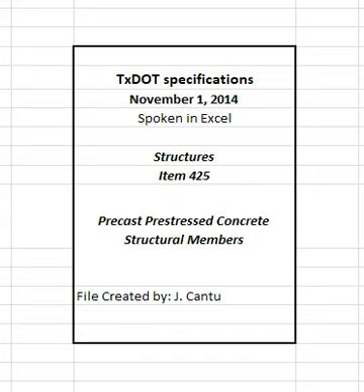Finish surfaces of beams or other members after slab placement in accordance with Section 420.4.13, Ordinary Surface Finish, and Item 427, Surface Finishes for Concrete. Correct beam discrepancies including, but not limited to, horizontal misalignment or variations in vertical camber, to achieve a satisfactory completed structure at no additional expense to the department. Correction may require replacement of the member.